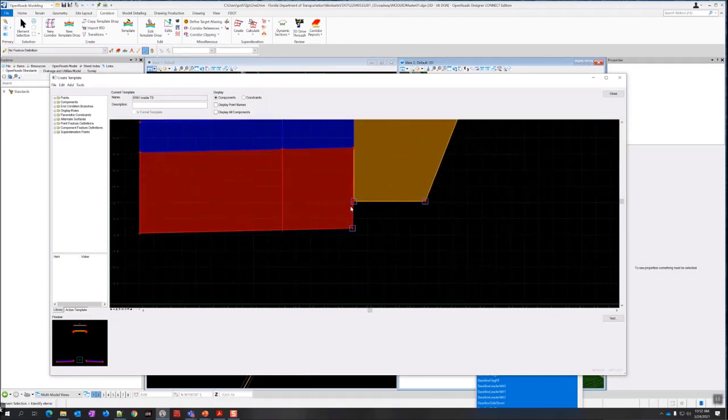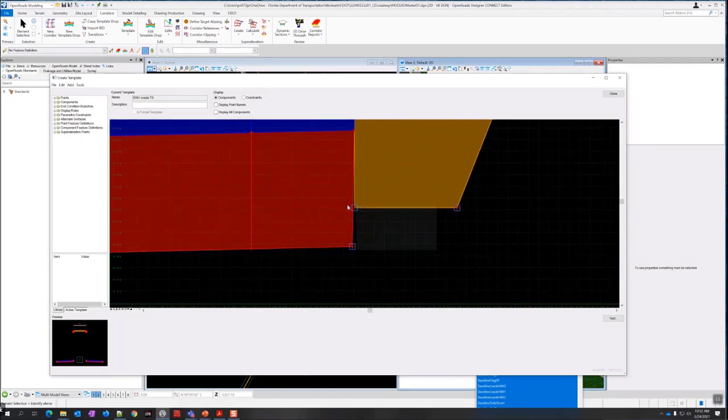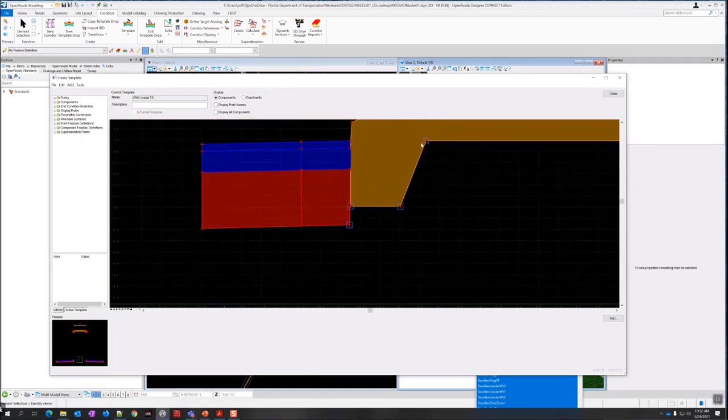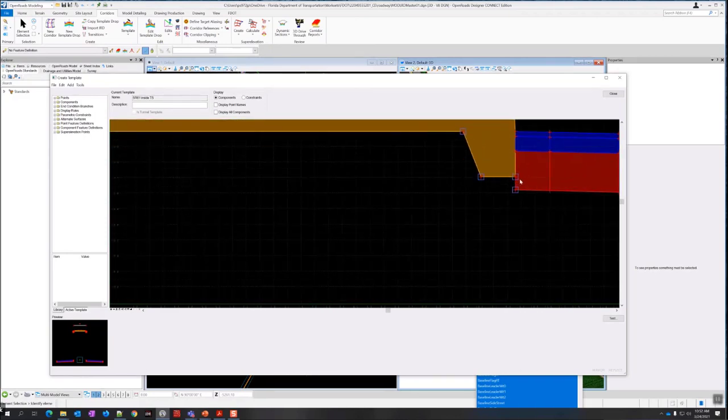But if you zoom in close here, these are already set to have that 0.01 offset. So you can see this is not vertical, even though in construction it should be vertical. Because of creating the DTM, we already set this to have a 0.01 offset. This one, of course, is not vertical, so you're right there. Same thing over here, you have the 0.01 offset.